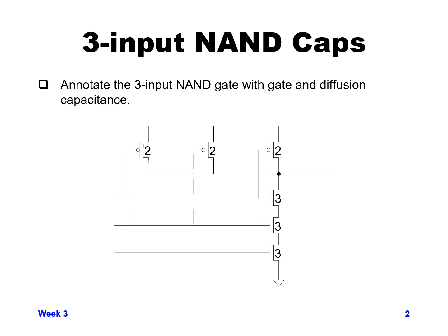So three devices in series that are size 3 have an equivalent resistance of a single size 1. And the PMOS devices, since they're each in parallel, we're concerned with the worst case where only one of them is on, so each one needs to be size 2 in order to be equivalent to the inverter that had a PMOS of size 2.